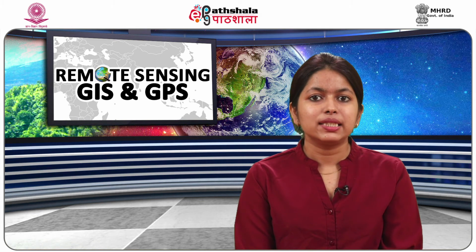In fire management, DTMs can be used as topographic inputs or as base elevation maps, which can be subtracted from canopy and vegetation heights to assess fuels. Topographic information such as slope, elevation and aspect can be used as a direct input into decision support systems such as FARSITE, which is a fire area simulator, and BehavePlus, which is a fire behavior prediction and fuel modeling system.